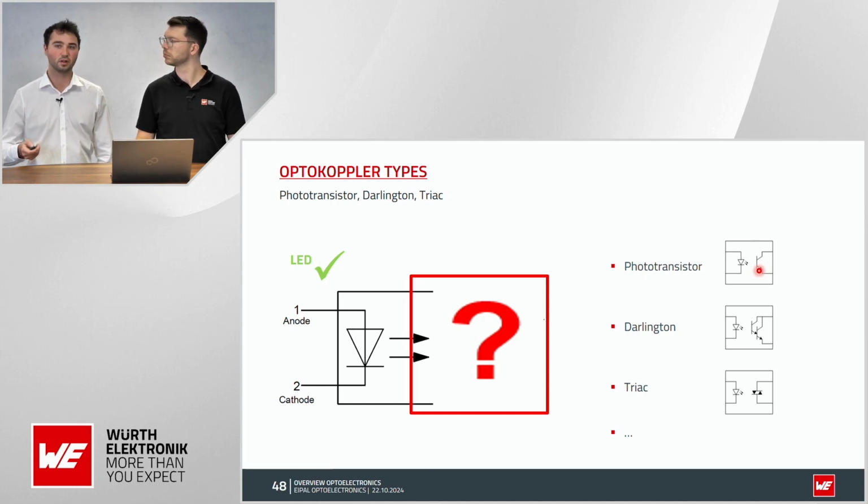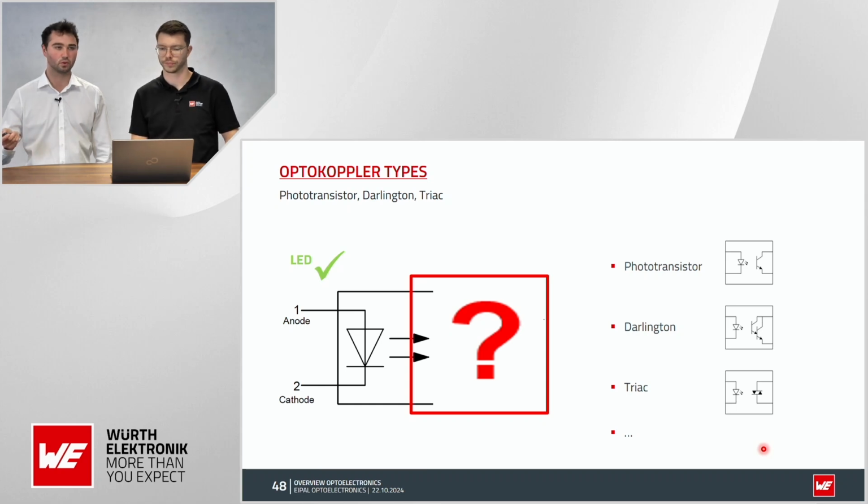So what you do for high speed, there are products like 1 Mbit or 10 Mbit, where you use not a phototransistor but a photodiode inside, which is much, much faster. And this is then connected to some kind of other transistor, which can then switch much faster. This kind of product is in development, but it still takes a few months to release it. But please let us know, or let your sales contact know, if you have any requirements there, then we can look at this already.